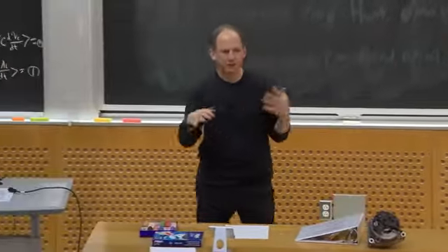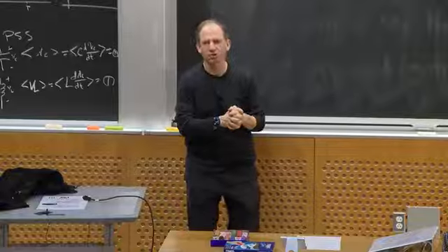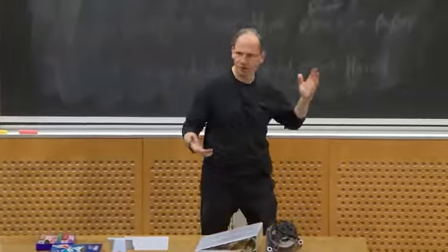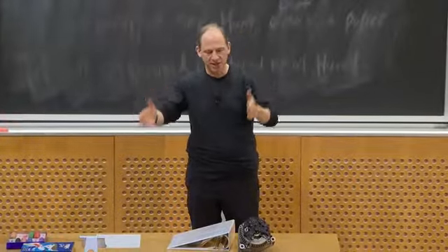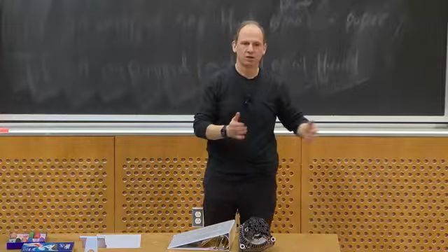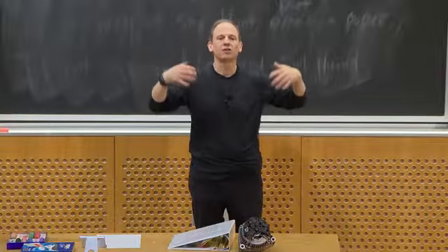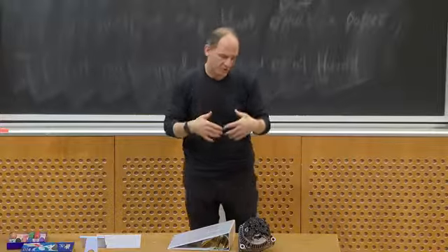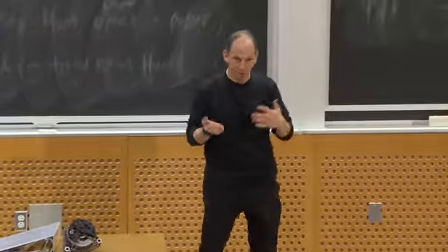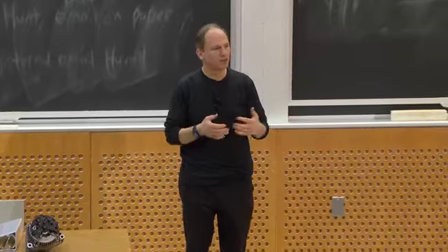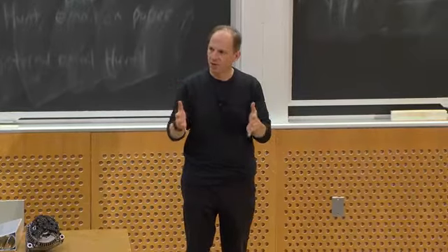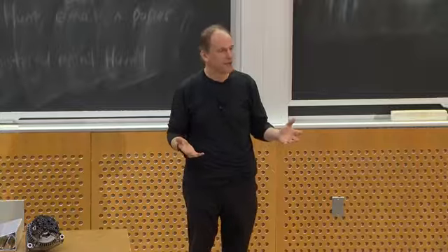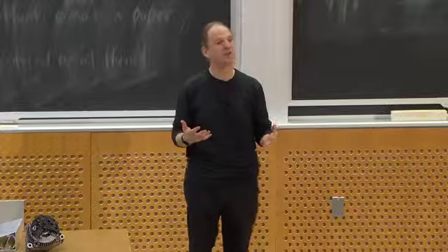The other idea we came up with last class was this notion of periodic steady state, which is sort of like sinusoidal steady state, except we don't have sinusoidal waveforms. It's basically that in each cycle that we're operating, the waveforms are just repeats of one another. It's settled down to this perfectly repetitive operation. Not all power circuits operate that way, but mostly they do. And one of the advantages of thinking about that mode of operation is that you can start to say a lot about the circuit waveforms.